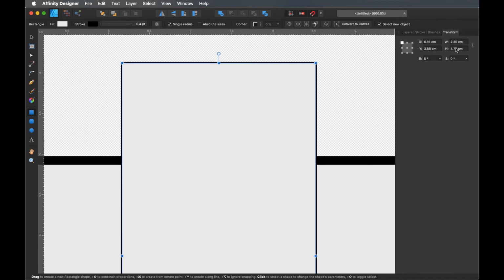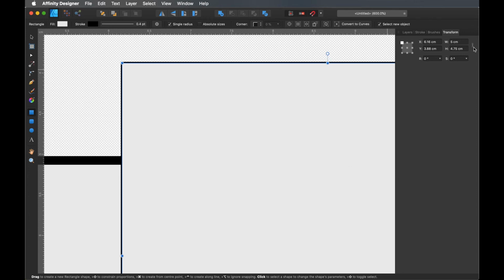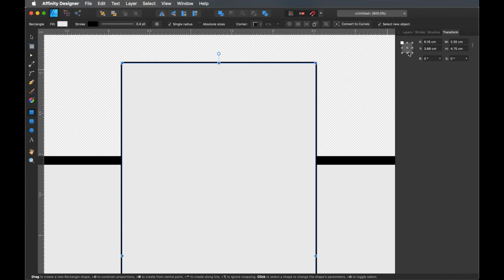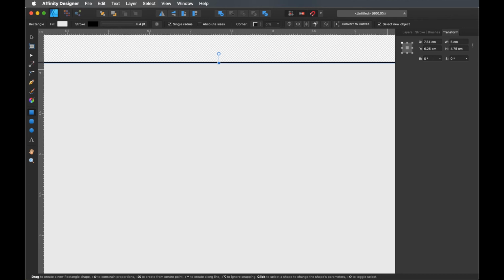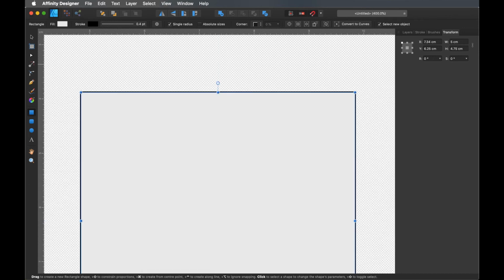And you've got your transform, which we can change the size very easily of something, as I've shown you previously. You can link it in all sorts. This is actually quite useful in the transform side as well, because when we're changing sizes or positions of things, we can tell it where to alter the size from. So this is obviously your center. It's just changed it from the left-hand corner. If we undo that and set it to the center and change it to 5 centimeters, there it goes all the way out from the center. So that might be handy on occasion. I do find that this is useful as well for double checking sizes and positions of things.